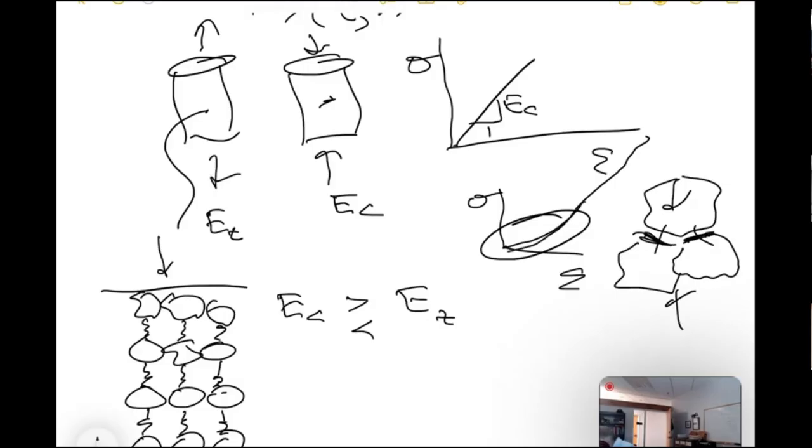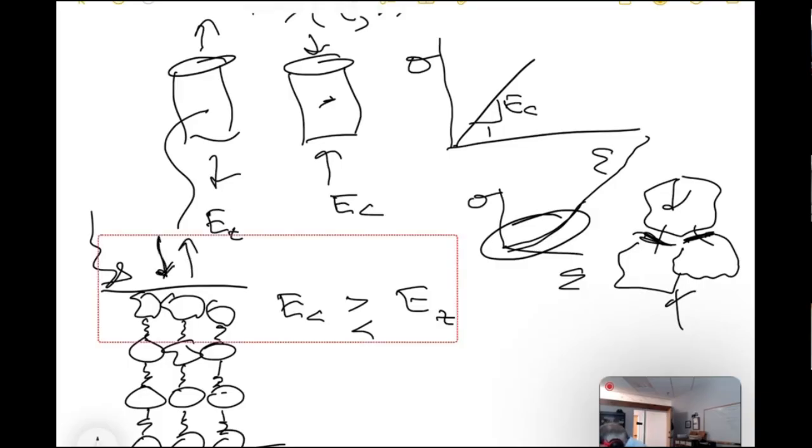Okay. Now go back over here. Here's a simple concept of a rock with grains and springs at the interfaces. Now if this was the system, every single contact has an interface. They're all closed to begin with. If I squeeze this, I'll get a modulus, and if I pull it, I get exactly the same thing. All we're doing is exercising those springs. It'd be the same thing. Springs don't care. But